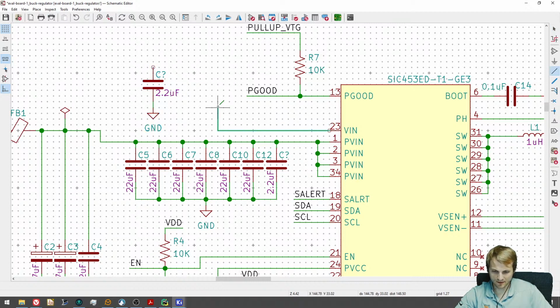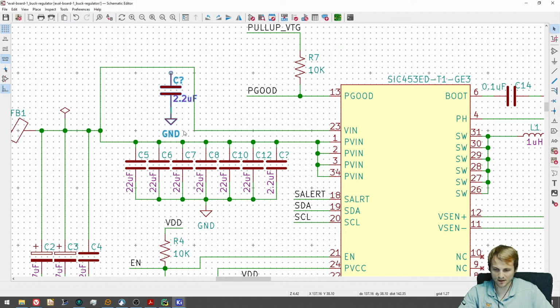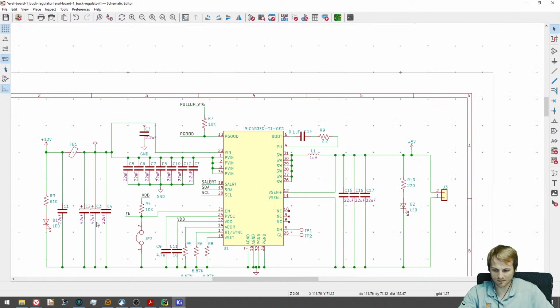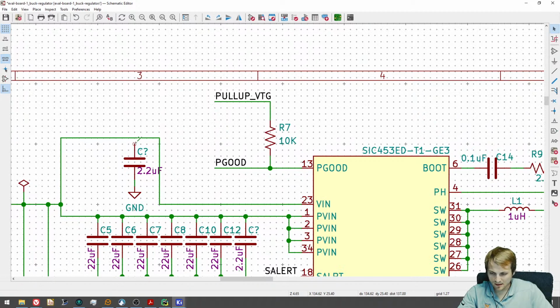And I know this obviously doesn't affect anything with the net because it's still connected here, but it just makes it more logical where the decoupling should go. The same reason why I put these over here, even though they're still all connected. I wonder what it says, how many they should have being necessary to put a decouple cap, so they just seem to say just one, so that's, I guess, all we'll do.